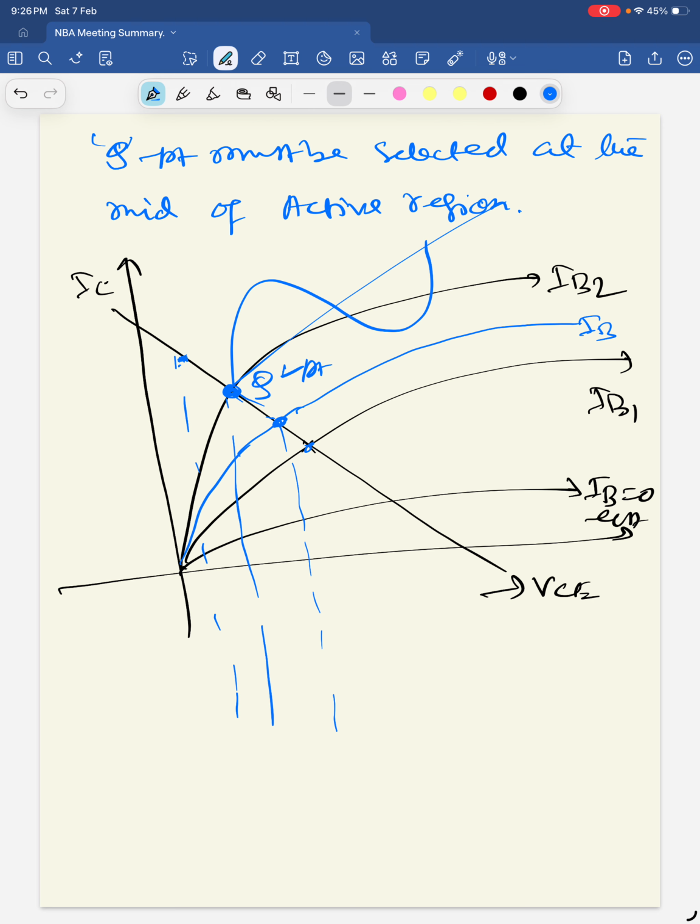But when it goes to the negative side, we will get some voltage of this type. So only for this negative half we are getting some voltage at the output. So that is the VCE swing. This is VCE maximum. For the positive half, we are not getting any output voltage.